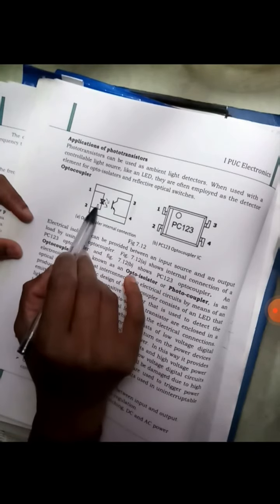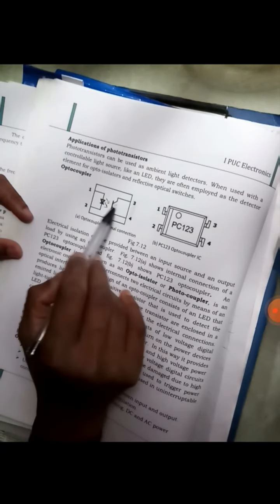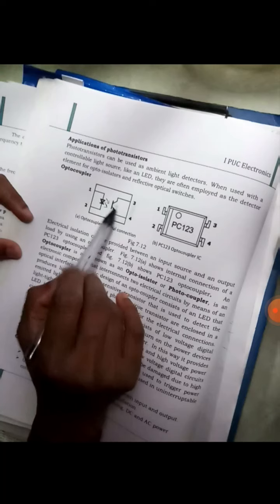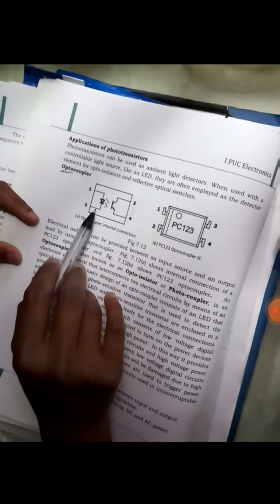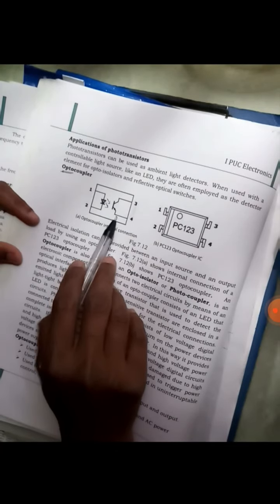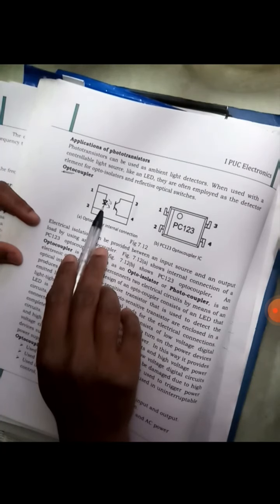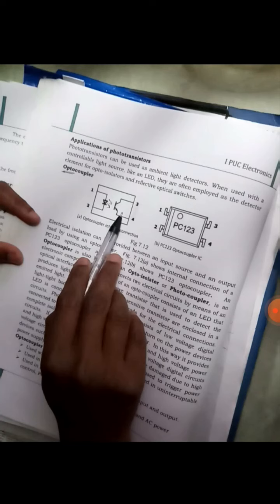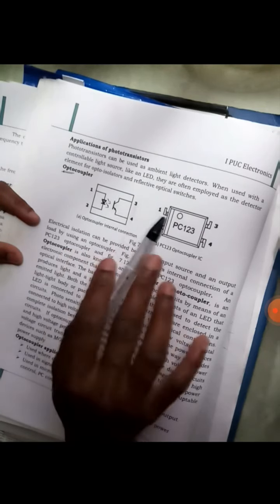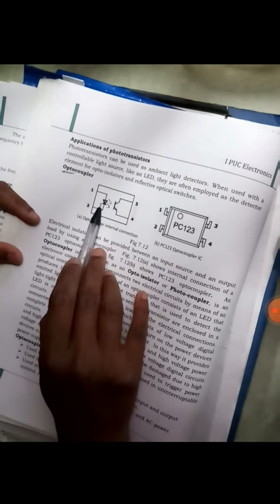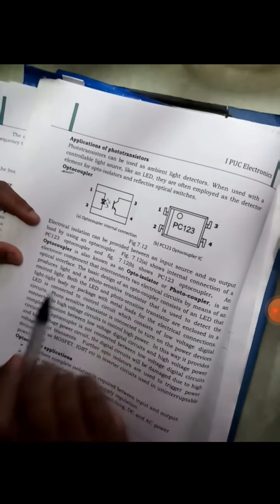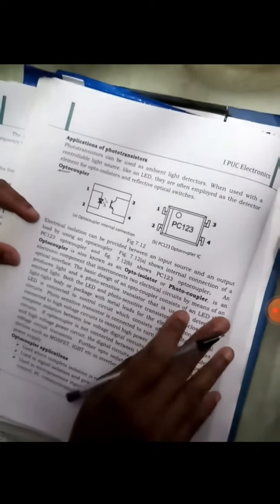But in an optocoupler there is a coupling, there is a connection between these two components. One is an LED, the other one is a phototransistor. What kind of coupling? Opto, that is something related to light. I give supply only to the LED. Once the LED starts emitting light, only then does the phototransistor start to respond. For this phototransistor to work, the light coming from the LED must fall on it. So there is no electrical connection, there is an optical connection between the LED, which we take as the light source, and the phototransistor, which could also be a photodiode. Okay? I have given the optocoupler applications in the notes, please look at them.